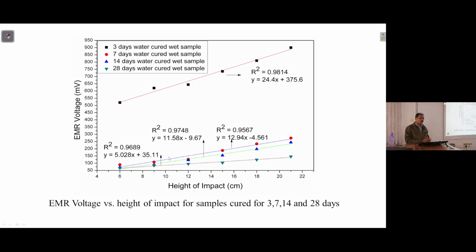So all in all, the point is the reaction is slow. It takes time. Initially, this part, if we consider, hydration is to a very small extent. It does not attain the strength. Everyone might have seen, when a structure with cement is built, you keep curing it for a pretty long time.